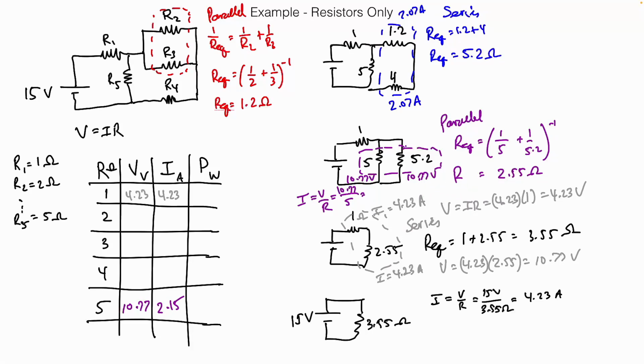Let me do this over here. Between these two, it's 10.77 volts divided by 5.2 ohms. And that's 2.07 amps. Did I get that right? My math could be very off. Pretty good? All right. It's just a number. But now that I know both the resistance and the current, I can find out the voltage of my 1.2 and my 4.